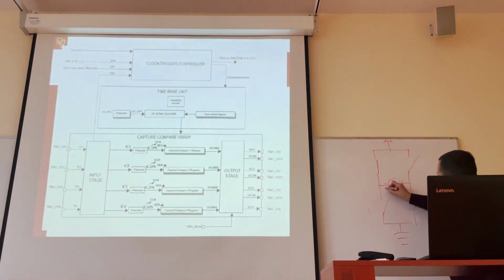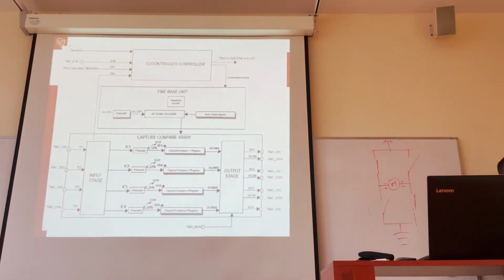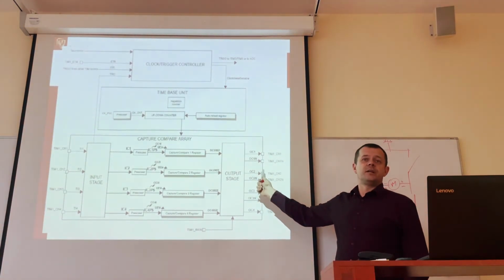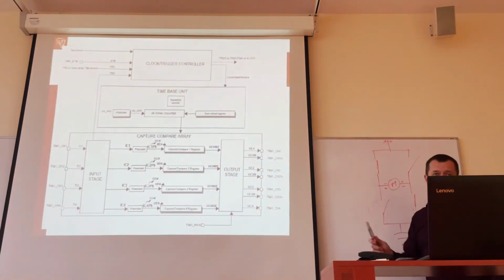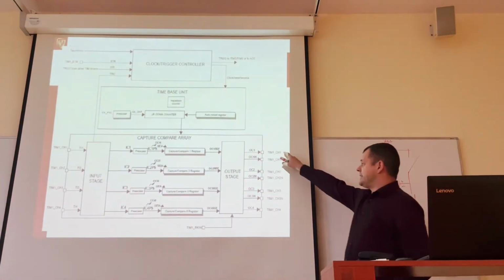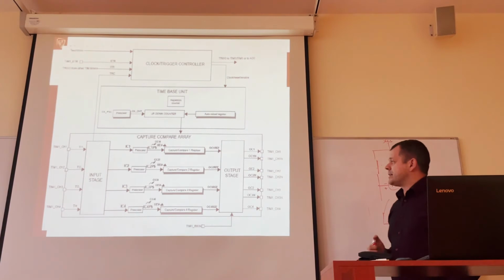And then we have plus here, minus here, which means that we can rotate the motor in the direction that we want. This H-bridge configuration is used for driving many different loads. But for this purpose, we need complementary outputs, and they are automatically generated, with some optionality, in microcontrollers. Again, this is something quite common.